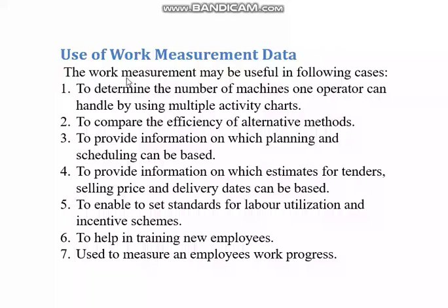Okay, now let us see about the use of the work measurement data. You will be collecting data with the help of this work measurement, and this data you can use for all these purposes. One is to determine the number of machines one operator can handle. In the method study you have studied about multiple activity charts, and now you have this data also, how much time each activity is taking.